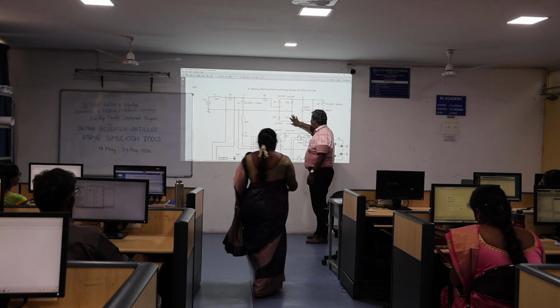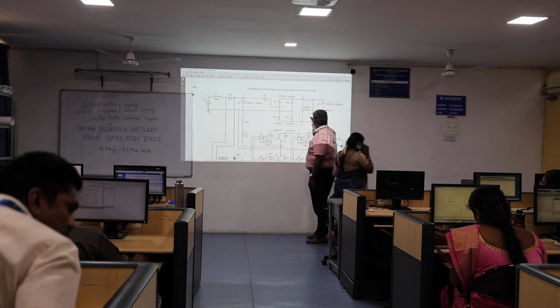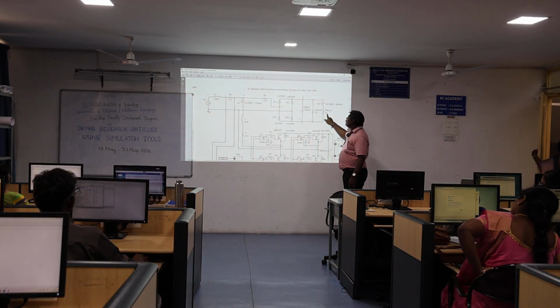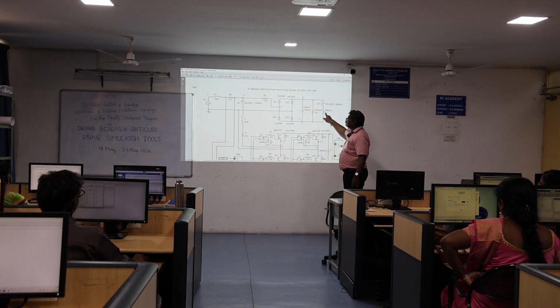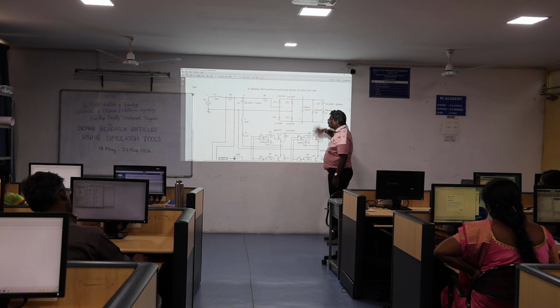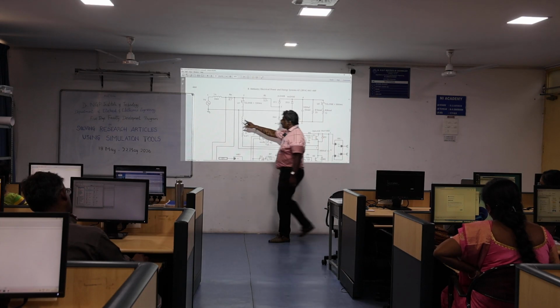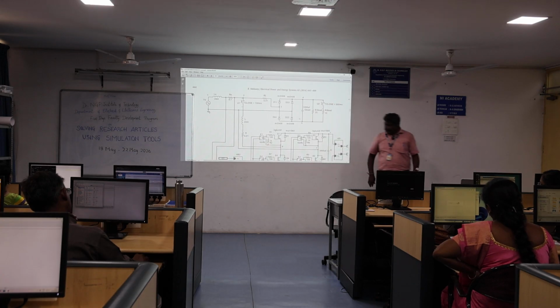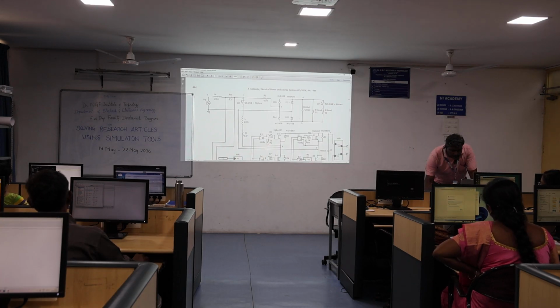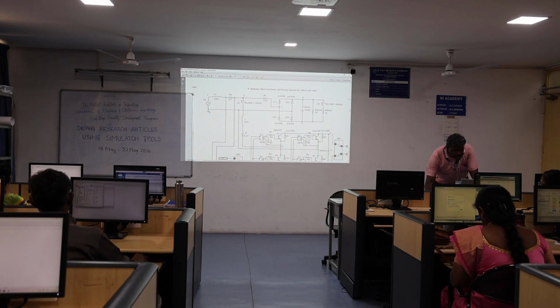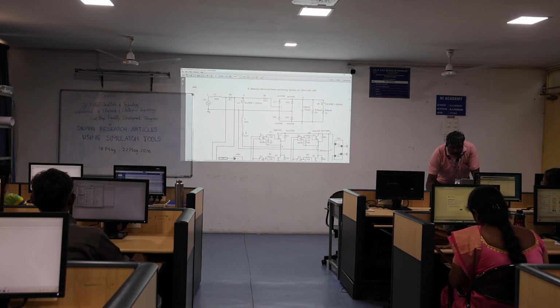For the diodes we can form it again with a capacitor, and for the load we have to change it automatically. At one particular time it will act as 10 ohm, after some time period it will be 25 ohm. For automatic purposes you can use a switch also. So first we will connect the source to some non-linear load, right? Let us take our Simulink. I want to construct this circuit. I need a source, 4 diodes, a capacitor and a load.